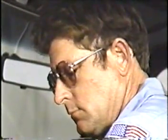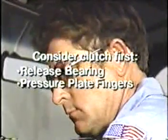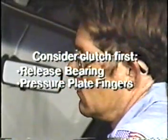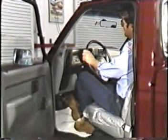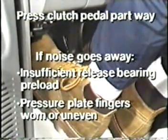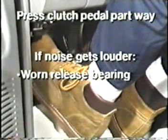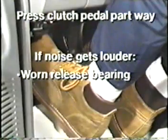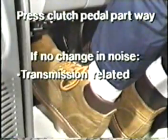Now, let's say you have a high-pitched squealing noise at idle with the clutch engaged. Begin by testing for possible clutch-related causes. A noise at idle could be caused by insufficient release bearing preload or pressure plate release fingers that are worn or uneven. You can isolate these possible problems by pressing the clutch pedal part way to put load on the release bearing. If the noise goes away, it's an indication of a problem with the release bearing preload or pressure plate fingers. If the noise gets louder when the release bearing is loaded, it's likely a release bearing problem. If there's no change in the noise, then it's probably in the transmission.